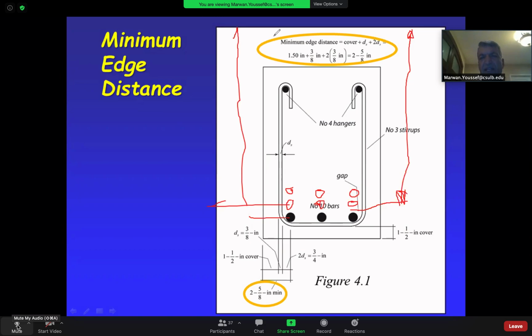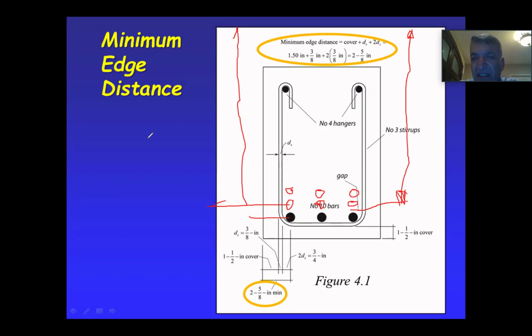Professor, what would be some of the reasons why you would put 1 layer or 2 layers? Because sometimes your load is high, and the size of the beam is limited for some reason.